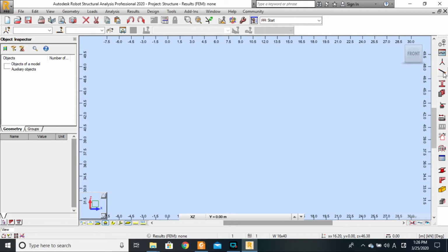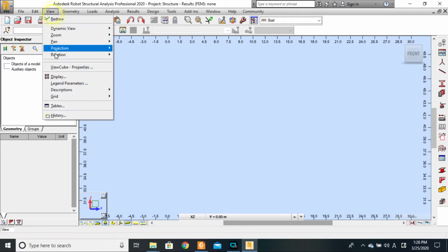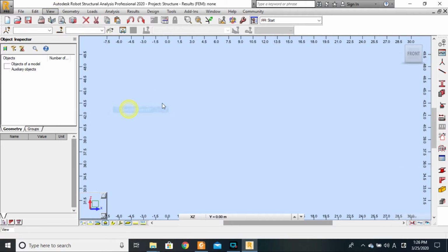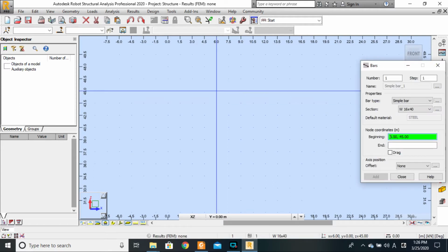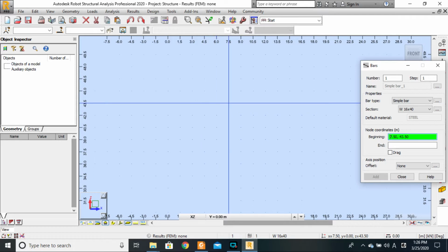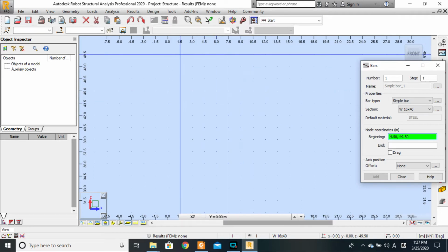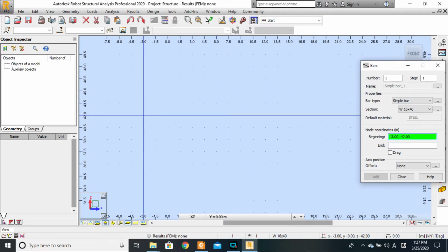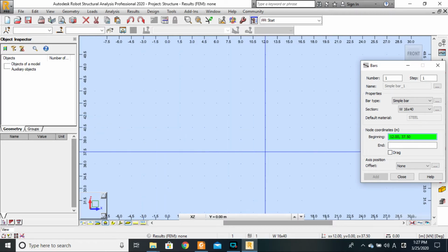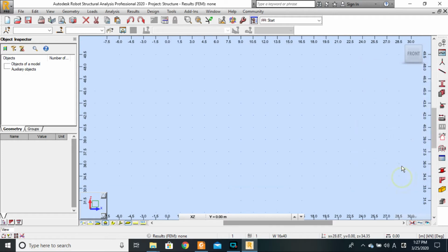Now let's try to put the grid back on, okay? Let's put it back on and move now. You see that my movement is now restrained to the points of the grid, which are spaced what? 1.5 meters following the x direction and 1.5 meters following the y direction. That is dx and dy.